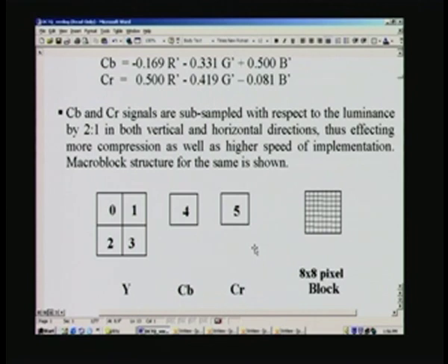So, compared to monochrome, for which we need only 4, processing true color needs 3 times that. That means we need 3 times the time, so the throughput is just 1/3 of what you get in monochrome. In other words, the resolution of the picture will take a hit, and you will have to scale it down by a factor of 3. Are you clear about this? If you process more blocks, it takes more time, that is what I am trying to say.